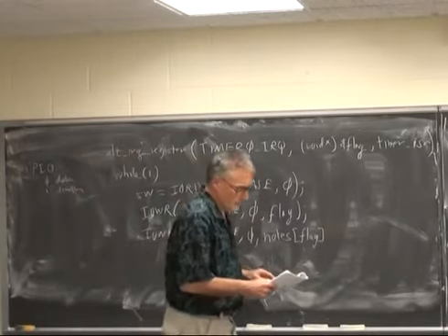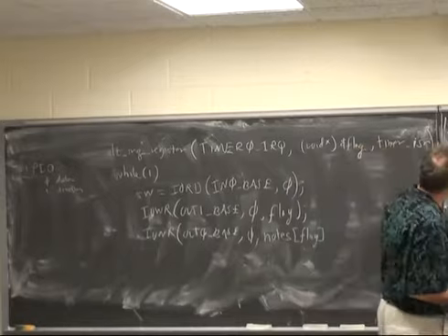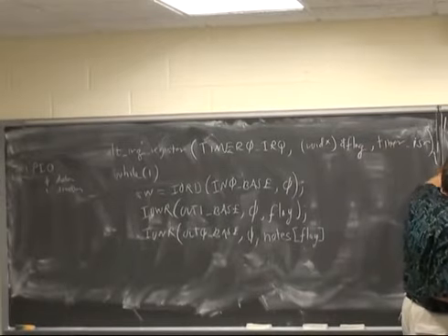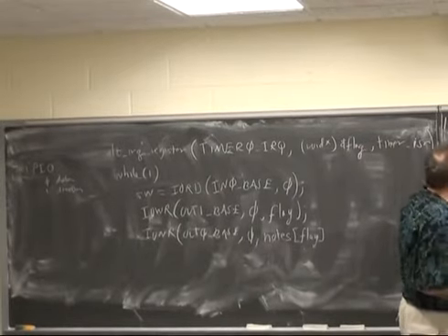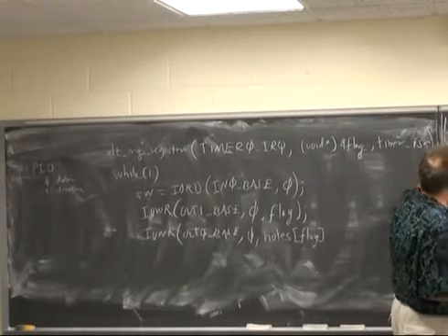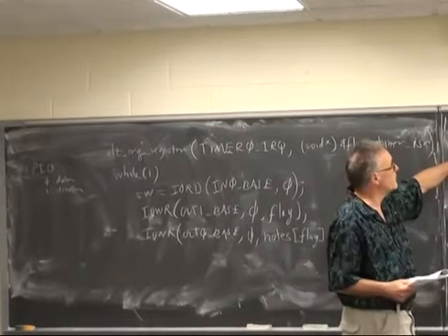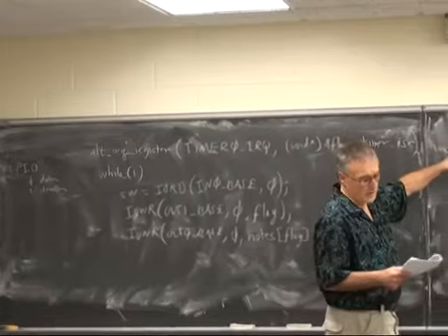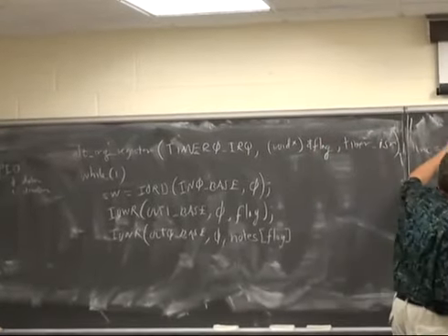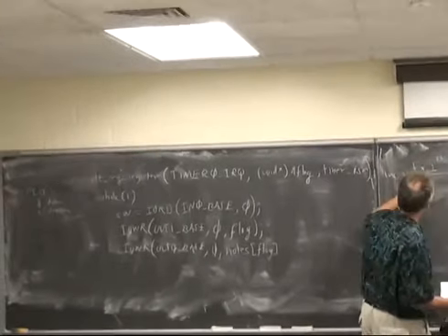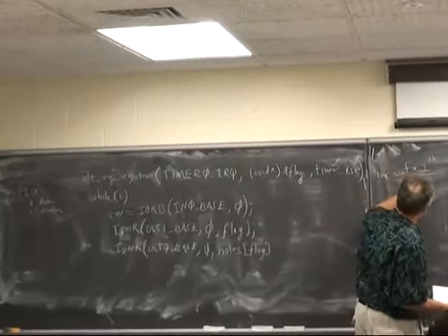And if you'll remember, I said that the increment corresponding to a frequency we desired of f is given by f times 2 to the 32 over the clock frequency.